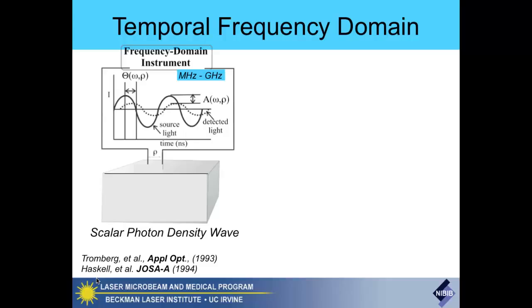So what we have to do is take the laser diode. We have to use a special little mixing circuit called a bias T. We bring it above threshold, and we hit it with RF. If we hit it with too much RF, you can imagine that there's this current-power relationship for the laser diode. If I bring it up above threshold, I'm going to get lasing. I can keep giving it current, and I'll keep getting lasing.